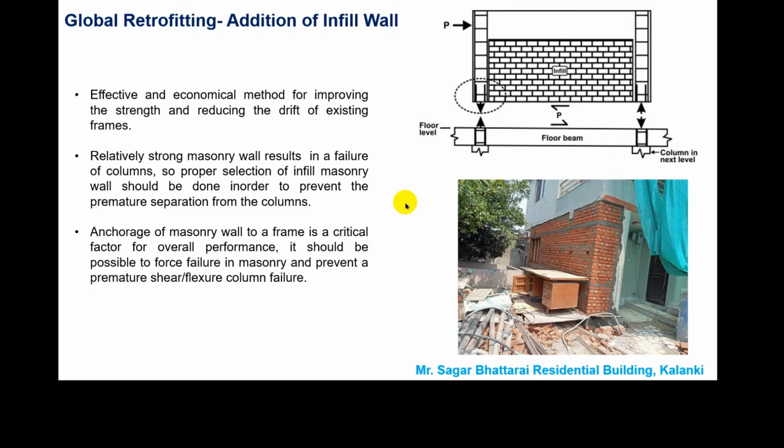But these things are not being done nowadays in practice while doing linear analysis, in the case of small or low-rise buildings, or high-rise buildings also, because the interconnection of the masonry wall to the column or frame is very complex, and without a proper connection, the behavior of the wall affects the actual response, or the shear or flexure response of the columns.